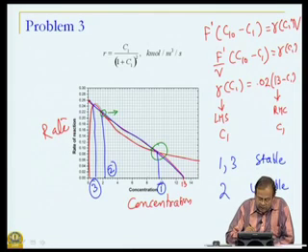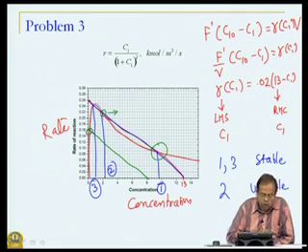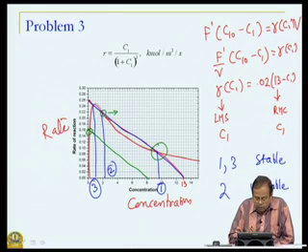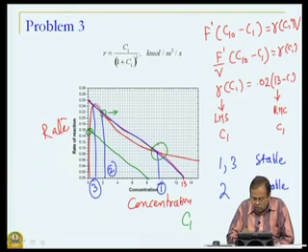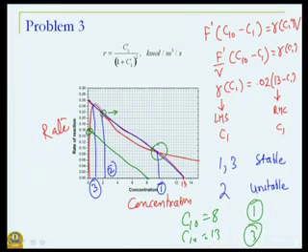So, suppose I make it 8, okay. The slope is same as this blue line and 8, so 0.16. So, we will have this as an operating line and the intersection point is only 1. So, between 8 and 13, for 8, that is feed concentration C1 naught equal to 8, we had only one steady state. If our C1 naught is 13, we had 3 steady states. So, between these two there must be a point where we shift from 1 steady state to 3 steady states, and what would that point be?